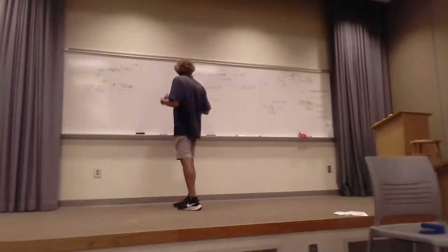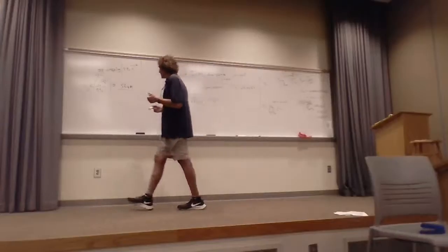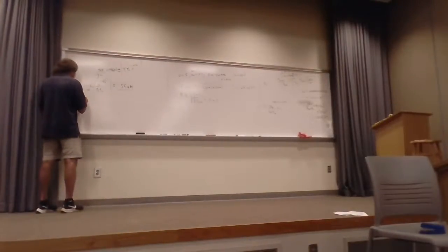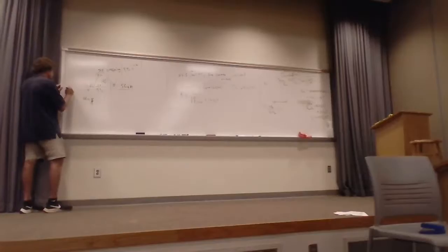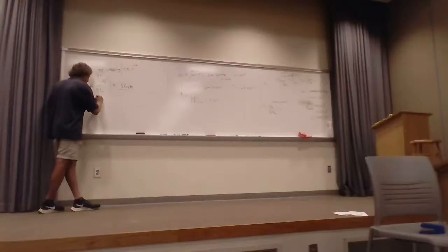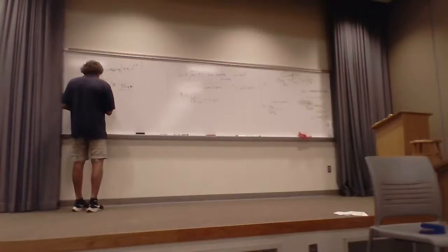Now, if you want to, you can take 56 microns and you can go to the definition of shielding effectiveness. I didn't calculate alpha, but you know that alpha is equal to beta for a good conductor, where sigma of the copper is much, much greater than omega epsilon. So that's equal to the square root of j omega mu sigma, well, let me do it this way.